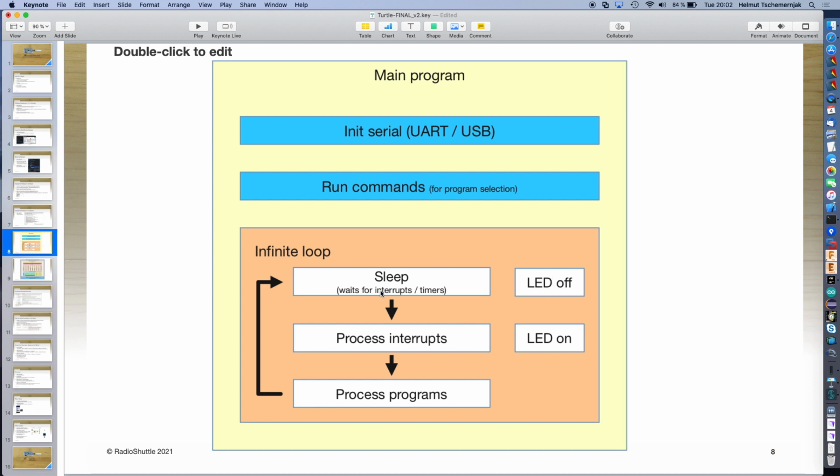This sleep will be a regular low power sleep, and if you specify node offline, which is a deep sleep configuration, then the sleep turns into a deep sleep, which means everything is turned off except for keeping the memory state of this MCU.